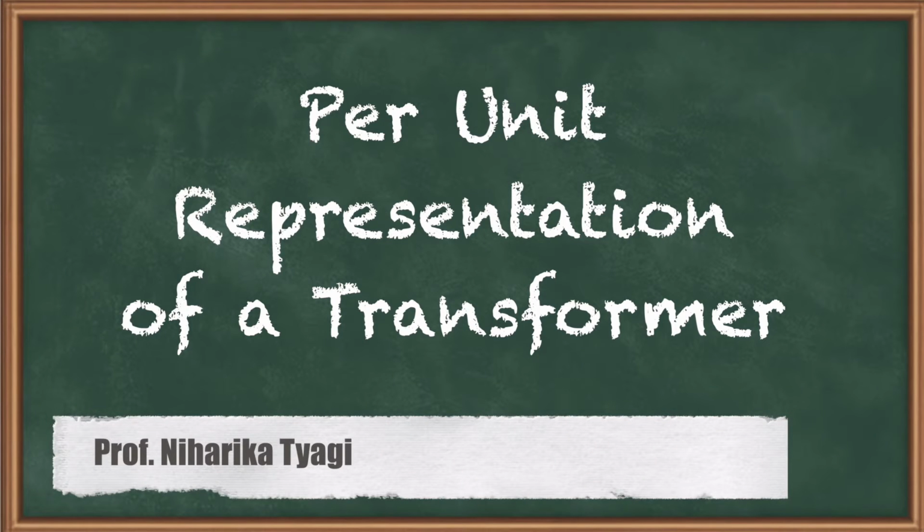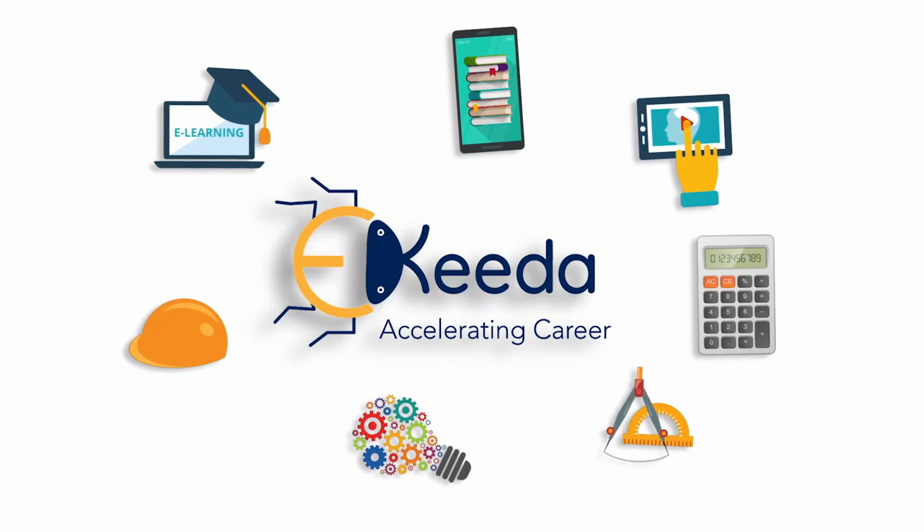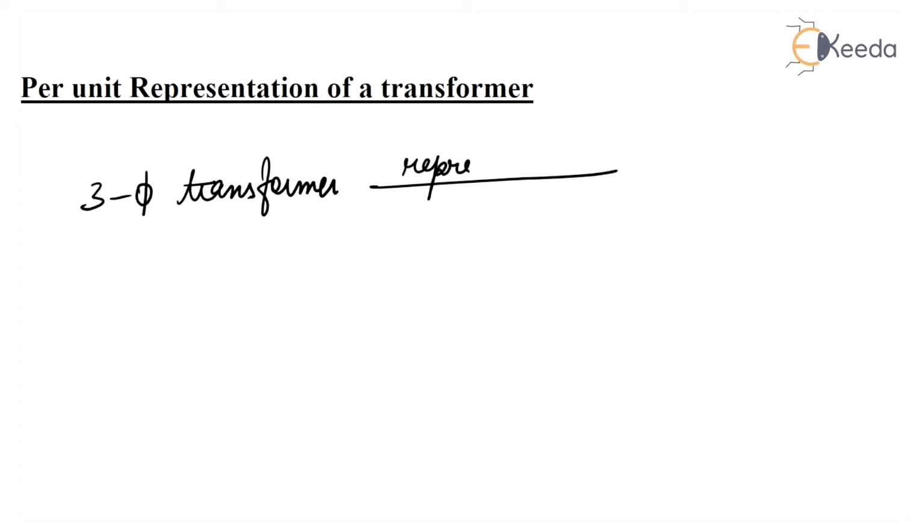Title of the lecture is Per Unit Representation of a Transformer. It has been discussed before that a three-phase transformer can be represented by a single-phase transformer for obtaining per-phase solution of the system.